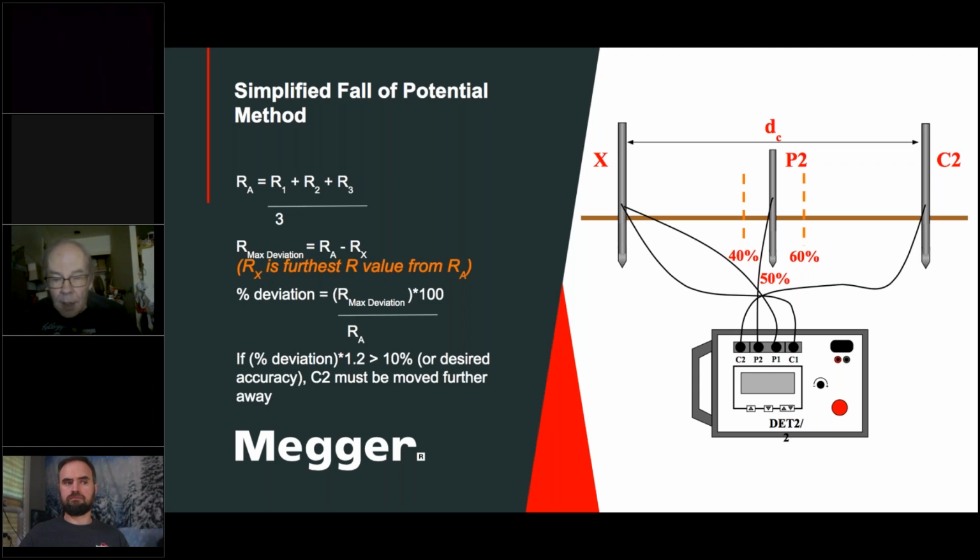You're going to take a measurement at half the distance, and then you're going to move in 10%, and you're going to move out 10%. And you're going to take those 3 measurements, and on the left side of that slide, you see you plug them into a little mathematical crunch, which in the old days you used to have to do manually.